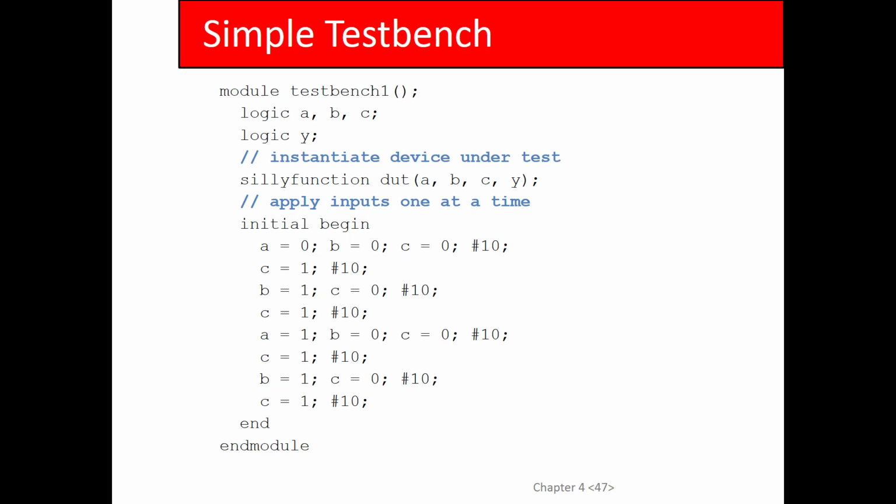Test benches are not synthesizable. They're only for simulation. One of the big improvements from Verilog to SystemVerilog is that SystemVerilog introduced a bunch of new non-synthesizable features that can be used for testing. That's the main difference. As far as the synthesizable aspect, SystemVerilog is virtually identical to Verilog. Everyone with me?